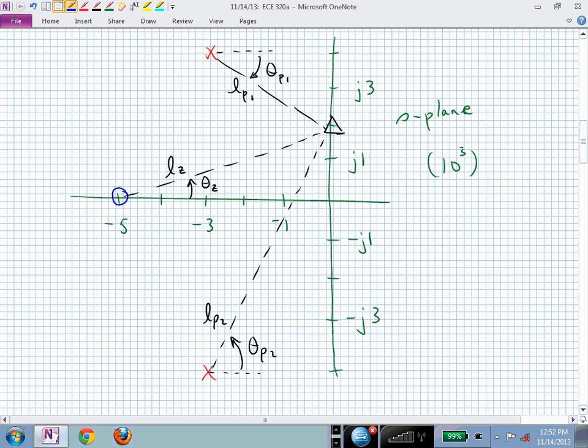This one had poles with real parts of minus 3,000. So now we have an e to the minus 3,000t with some cosines and sines. And what's the frequency of those cosines and sines? 4,000, isn't it? But that's not influencing our tau. Our tau is basically how far into the left half plane do we have to go before we reach our first pole. That's our slowest pole. In this case, it's e to the minus 3,000t.